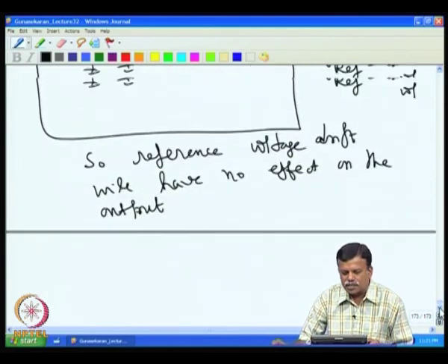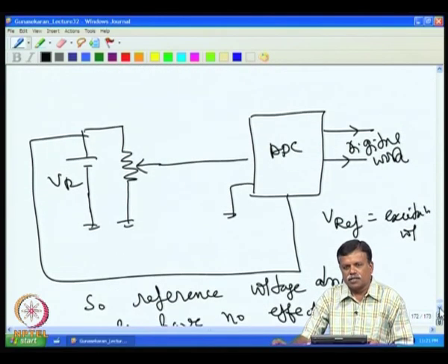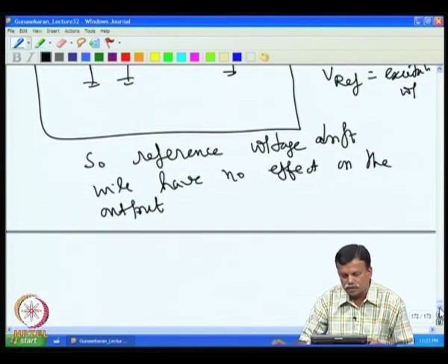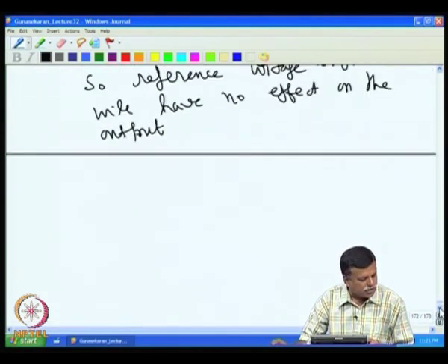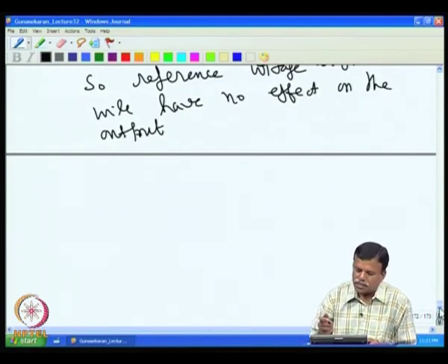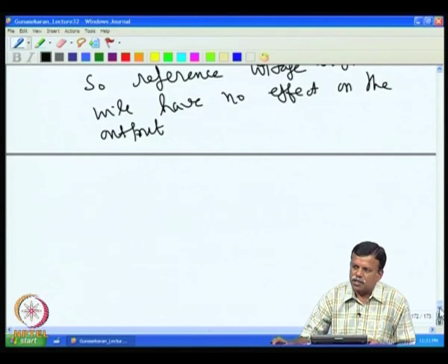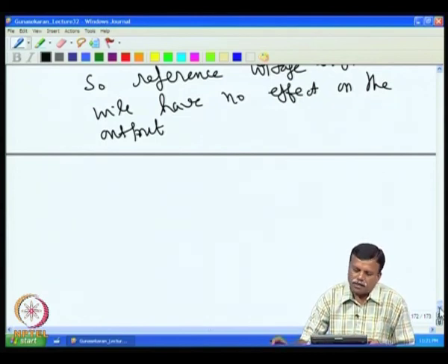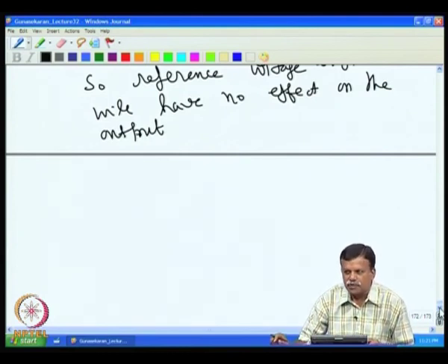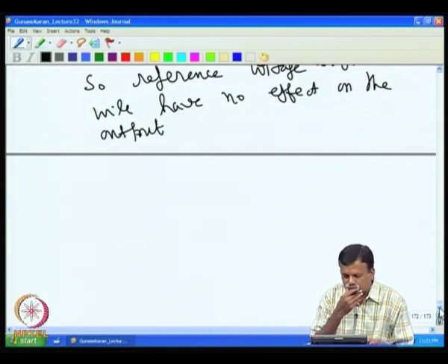Now we have processor based A to D converters, which are extensively used in the industry. So one has to worry about what errors are involved, because most people believe that if it is an 8-bit converter, you will get 8-bit accuracy. That is no more true. So when you are using a processor based system with an inbuilt ADC, one has to clearly verify from the data sheet what is the actual error associated with the particular converter.